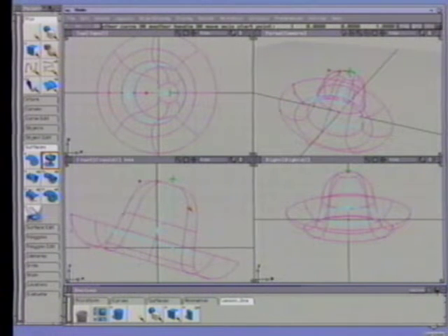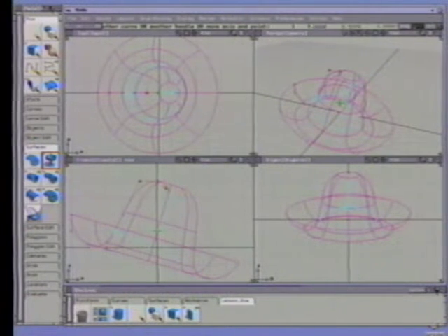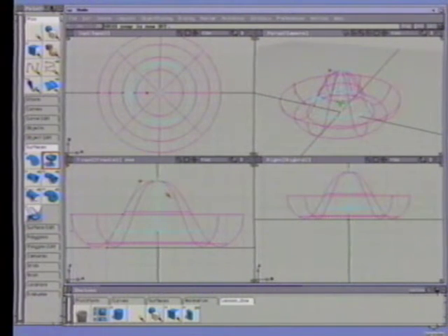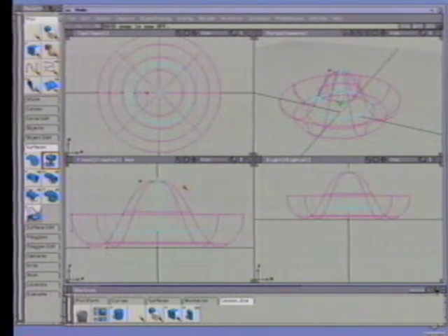The revolve is again regenerated using the tilted axis line. Click the top cross of the axis line. Press the Alt key to temporarily turn on grid snapping. In the front window, click-drag the point so it is directly above the origin to reorient the axis. The surface updates to its original position.